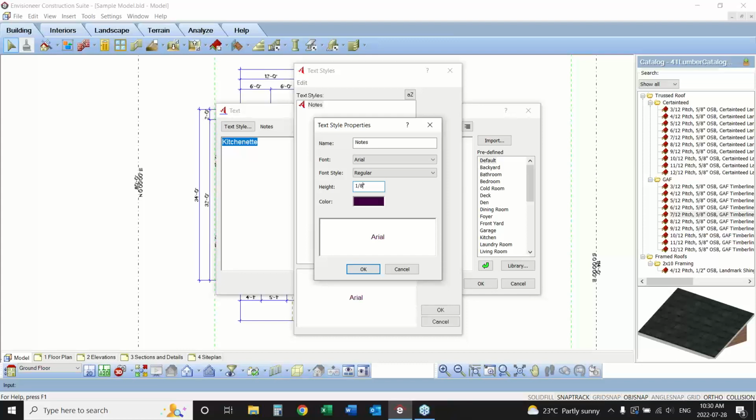When you're hand drafting, you don't change the size of your text when you're working on a detail, a floor plan, or a section. A sheet of drawing always has the same height of text, so it looks consistent and it looks nice on the drawing sheet. It doesn't get blown up, with one size of text huge over here and smaller over here.